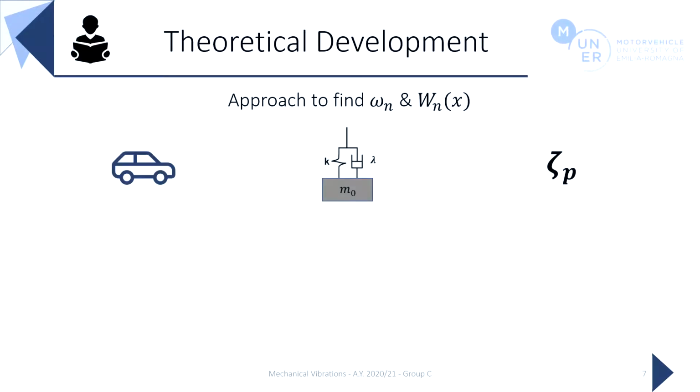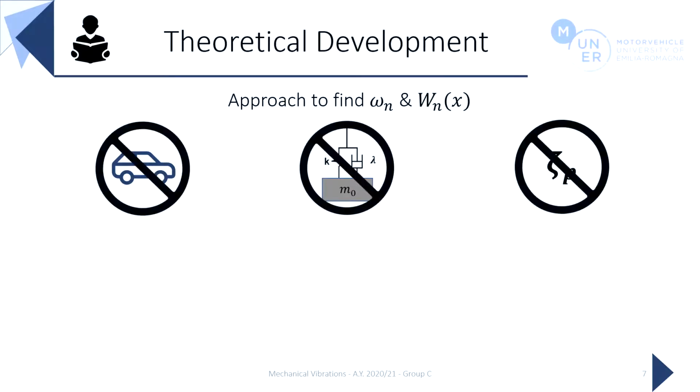Natural frequencies and the mode shapes have been our prime focus, as they are an important milestone to determine the vibrational behavior of the system. To analyze them, the bridge has been examined without the DVA and free from excitations. In addition, the structural damping of the beam is taken to be zero. Admittedly, this will lead to the obtainment of modal shapes and natural frequencies that are not proper of the real system, as the presence of the DVA and the structural damping will somehow alter these values.